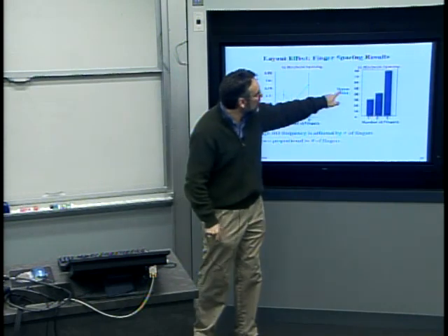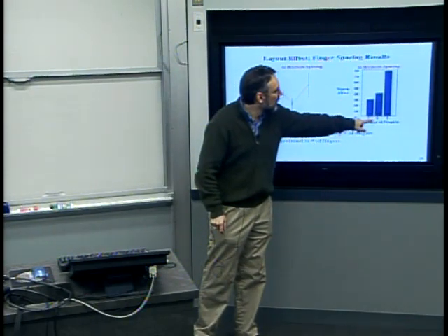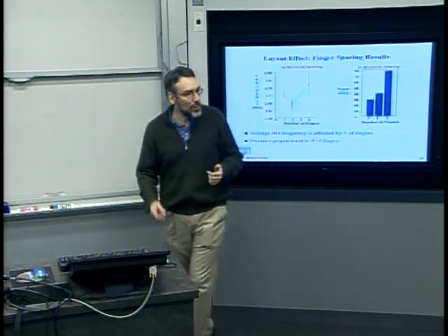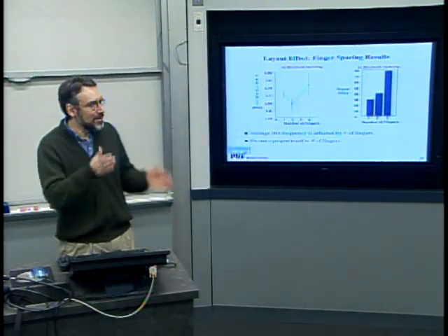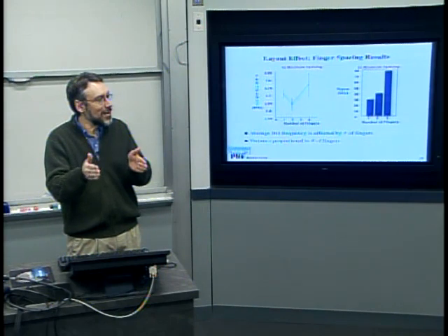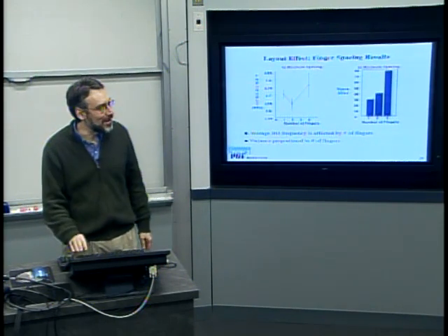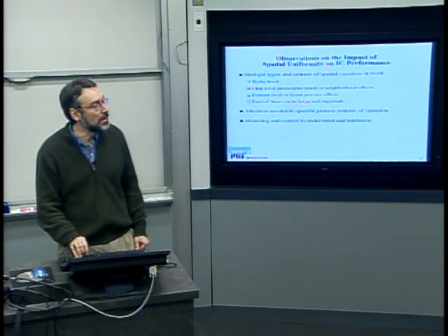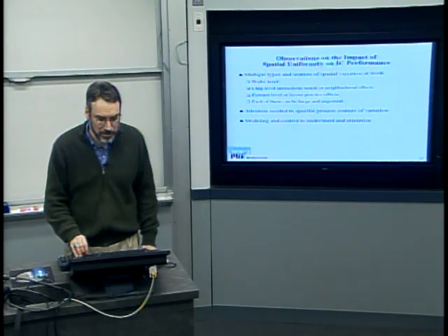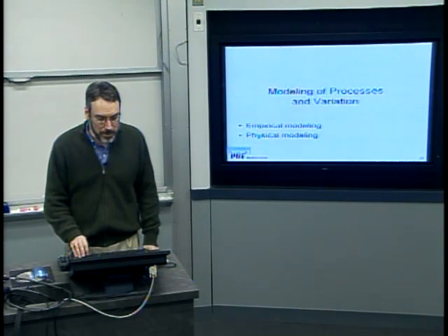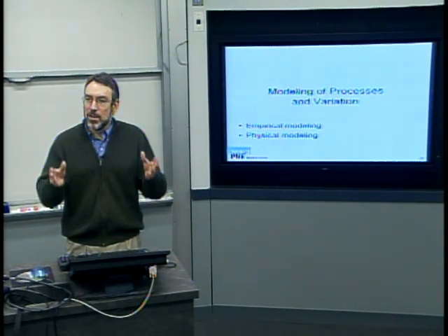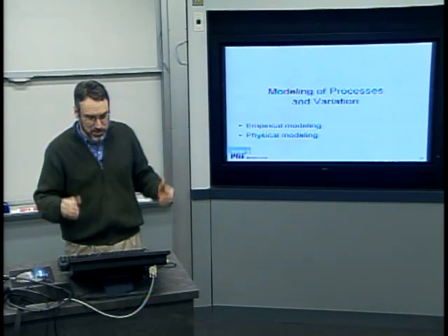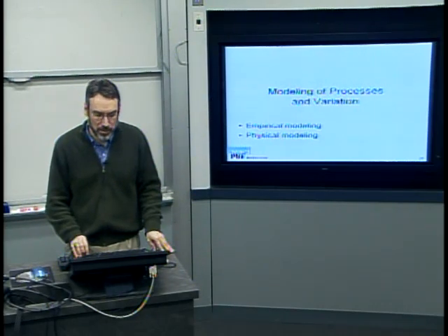If we look at the sigma with 1 finger, 2 finger, or 4 finger, we found a proportional increase in the variance with more opportunities for variation by the fingering. So that was an interesting implication for some design kinds of effects. Okay, so that's an example where design of experiments could be used to come up with test structures and characterize and split out some of these sources of variation.